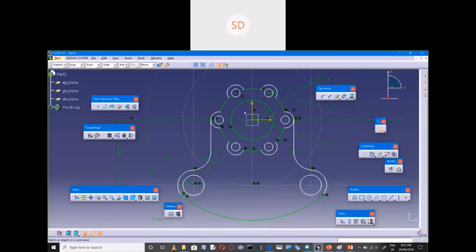Okay. And I'll go for a circle. That is construction. I'll take this as my center point. Right. Of circle, normal. Now we can just draw here. How much is it? The radius is 10. I think now it is clear. Right? Because of the dimensions, it has been shifted. This circle is shifted. The circle became tangent to this one when we selected the dimensions. Okay. Now it is perfect.